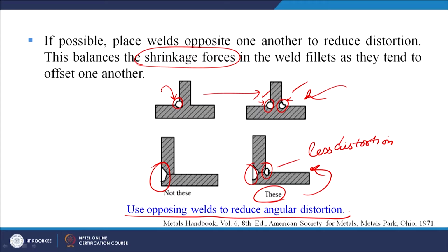So basically we can see that there are a number of other such guidelines. These are the most simplistic type of guidelines. Just by looking at the diagram you can easily understand that yes, this will be somehow beneficial. A number of such guidelines have been listed, and if we take care of these guidelines during our designing process, when the parts are being designed which have to be welded later on, if we keep them in mind, ensure the uniform thickness of parts to be joined, make the welding away from the surface where the machining has to be done, we will be able to design the product or the parts of the product in such a way that we will have absolutely no problem when we are going to join them properly.